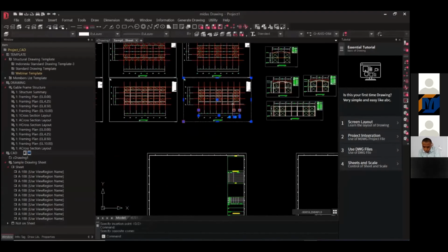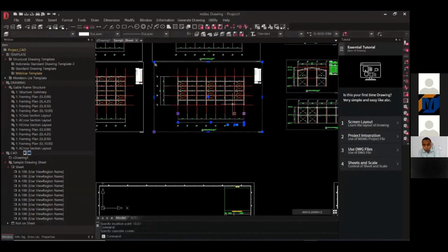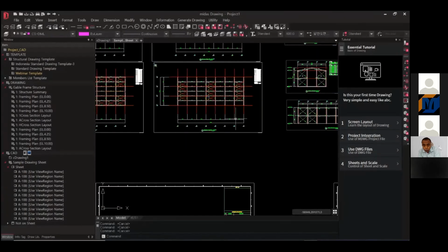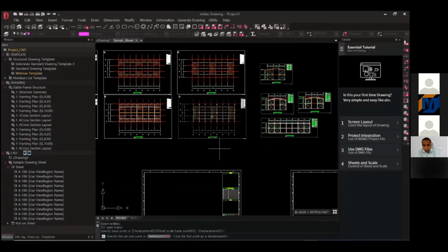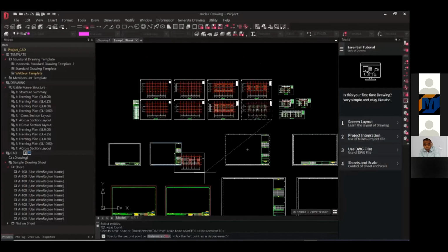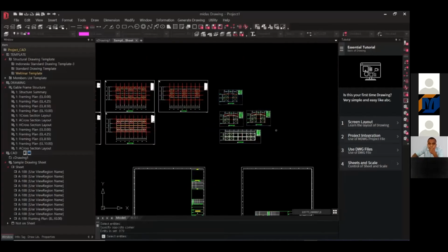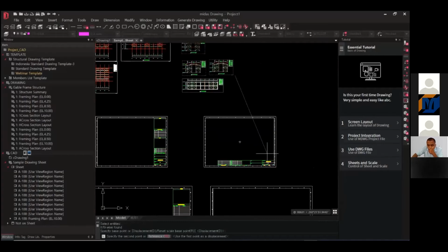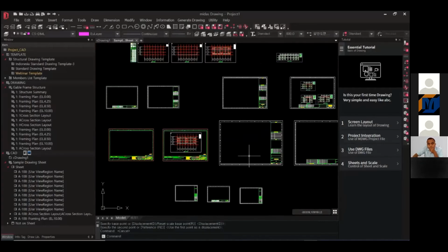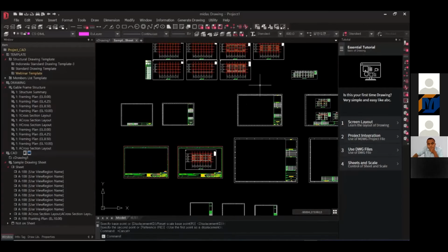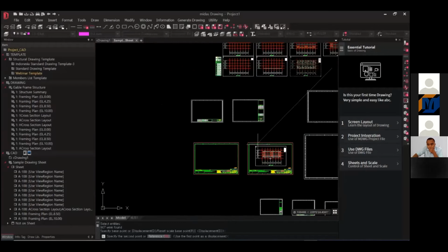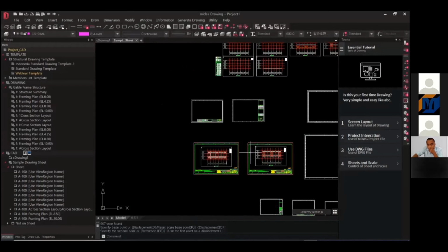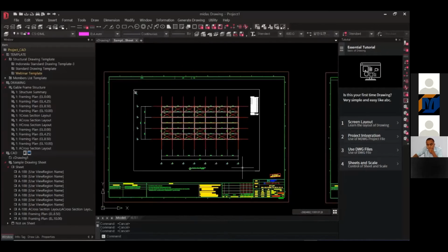Now, place the imported drawings in the proper position on each sheet. In this case, use the Move function. Since it is in CAD mode, you can use it like AutoCAD from now on. Let's arrange the other created drawings in order. You can adjust the scale information. If you do not modify the scale, you may prepare for various sizes in advance.